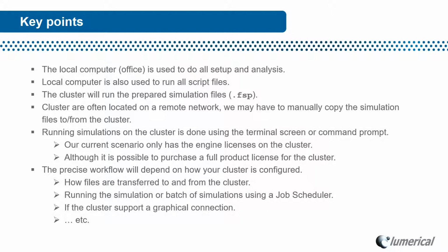Okay, let's look at a few key points, then I'll show a simple example. First, it's important to understand that the local computer, which has the graphical CAD license, is used to do all setup and analysis of the simulations. It's also used to run all script files. Next, the cluster, which only has engine licenses, is only used to run prepared simulation files.